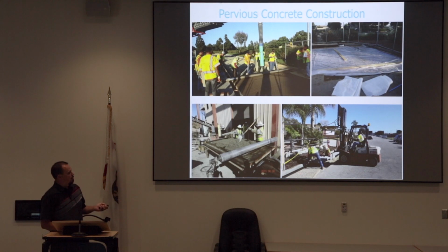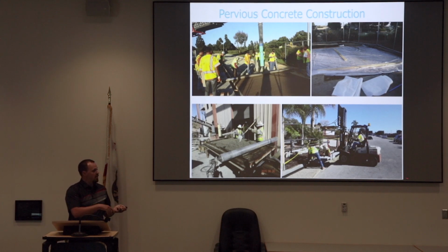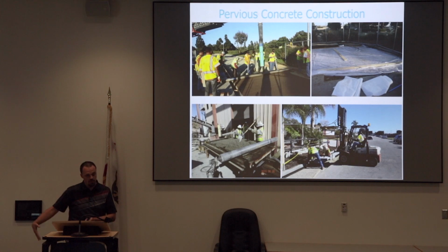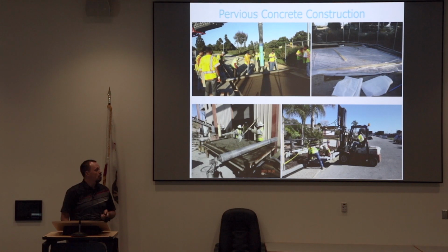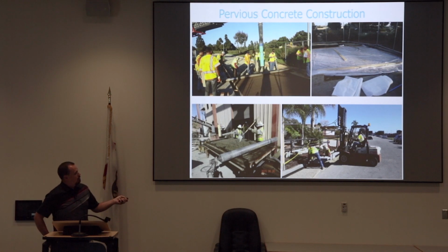Once you build your trench, you do your backfill and compaction of your rock aggregate, then these basically snap in like Legos. You drop them off, put chains in these lifting rings, you drop it in, slide it up against the next one, put in these spacers, slide in the next one. So you can basically do a full street in a day, no problem, once you have the trench and everything ready to go. The benefit of these too is for O&M.